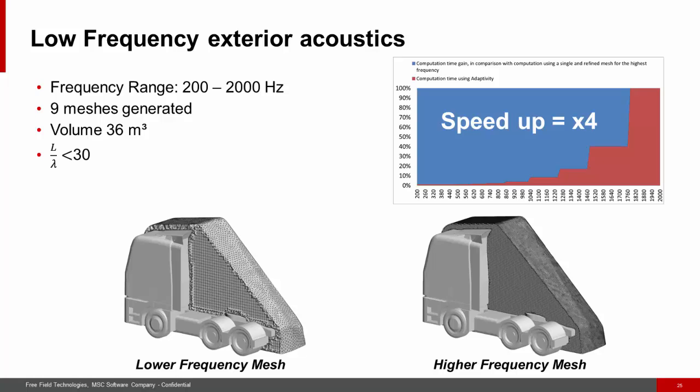For the low to mid-frequency approach, we have solved this problem and we computed the acoustic radiation from a monopole placed at the exhaust position around here. The mesh adaptivity, so first we have used Actran Acoustics and we have used the mesh adaptivity. The ground buffer plane has been taken into account automatically by the meshing tool.